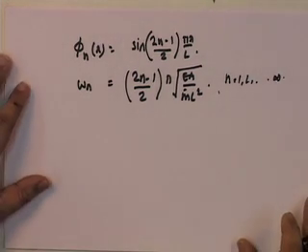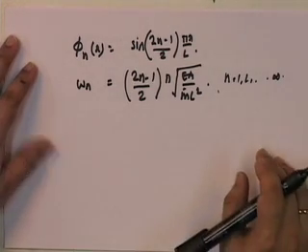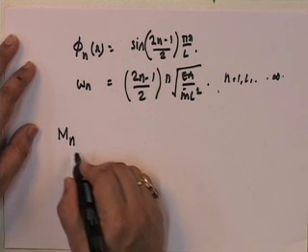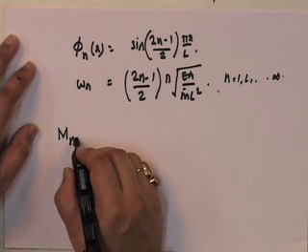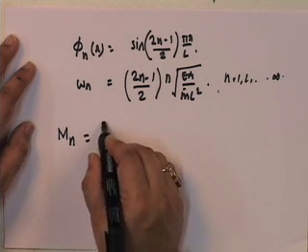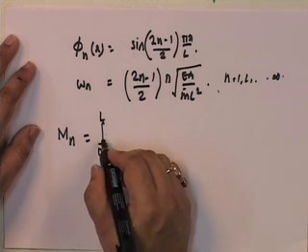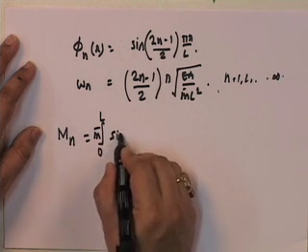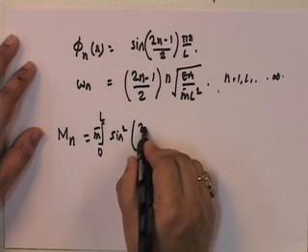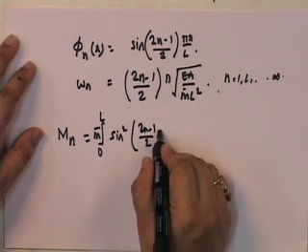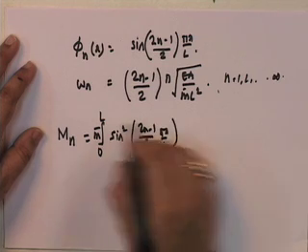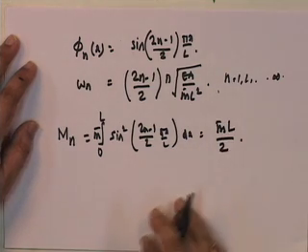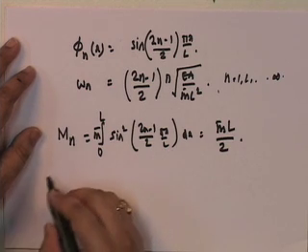Now, the thing is to find the generalized mass. Mn is equal to the integral from 0 to L of m bar times sine squared of (2n minus 1) pi x upon 2L, the same thing that we did last time, and we get that it is equal to m bar L upon 2, exactly the same way we have done it last time.